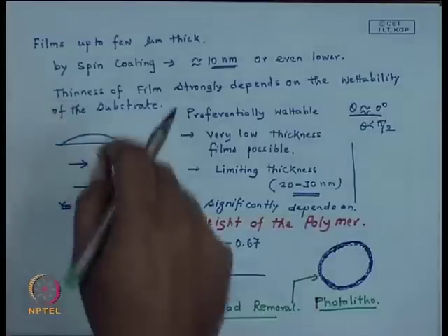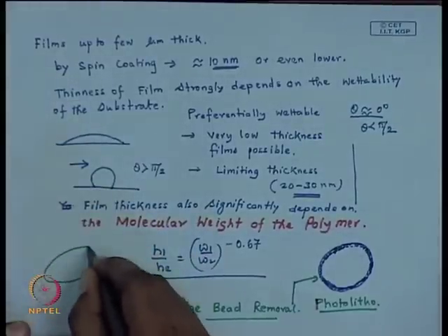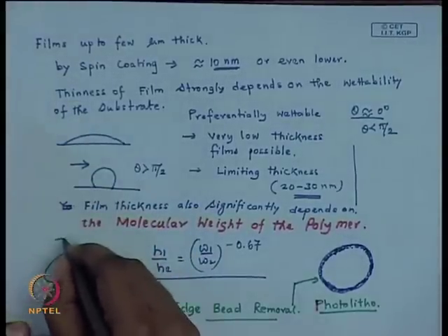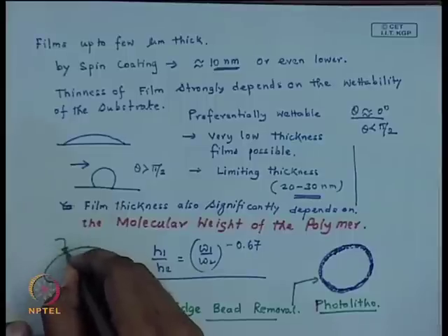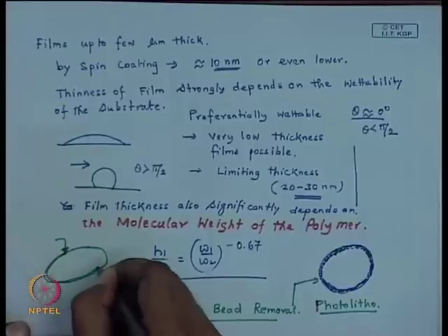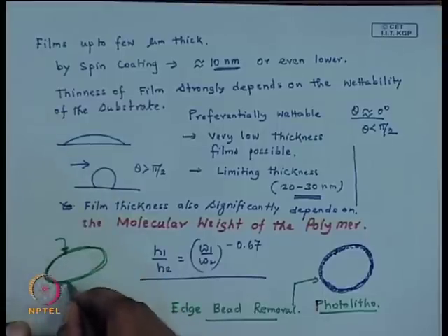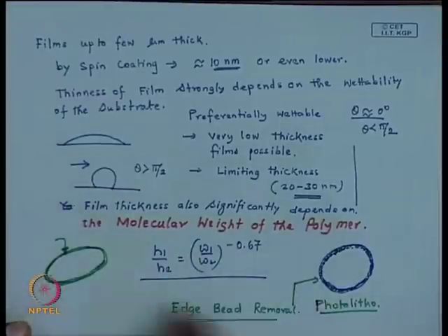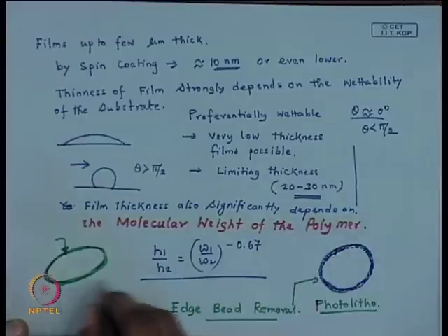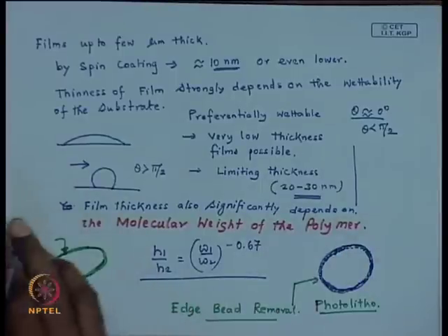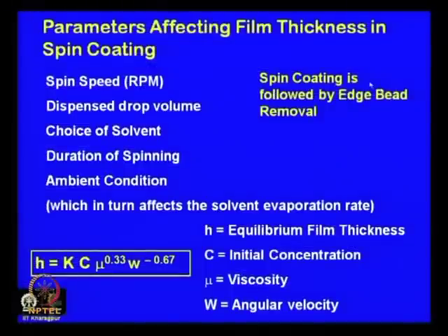You can have a disc like this, and the same spin coater with some attachment can be used so that you have a solvent flow only along the periphery. You rotate it at very low RPM, and the unevennesses along the periphery get washed away, resulting in a film which is smooth and does not have undulations at the edges, which would affect the subsequent stages.